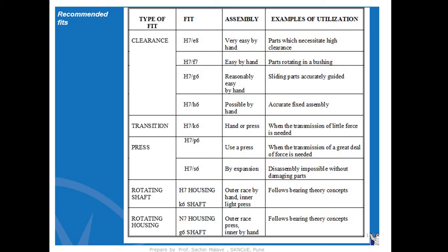Then H7 G6, reasonably easy by hand, sliding, parts accurately guided. H7 H6, possible by hand, accurate fixed assembly.